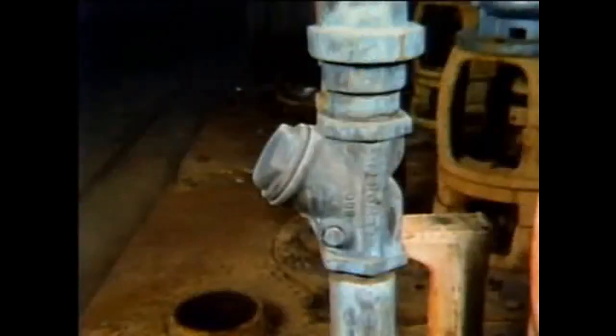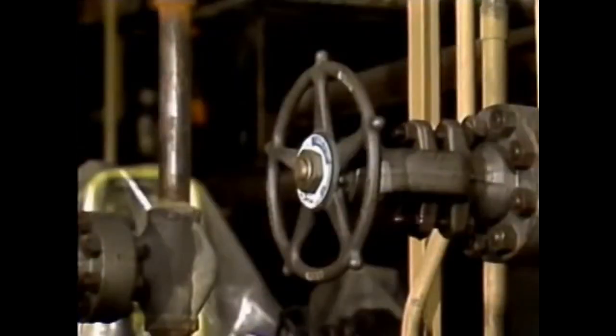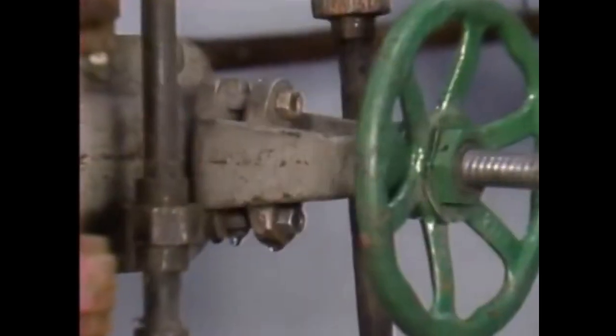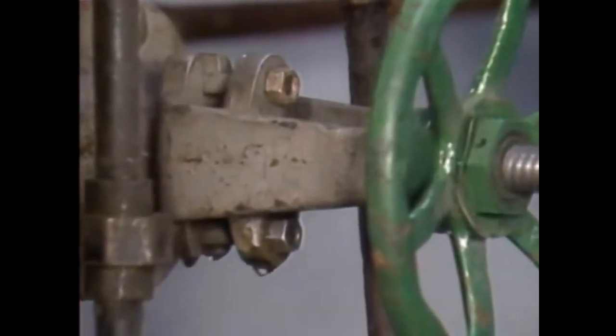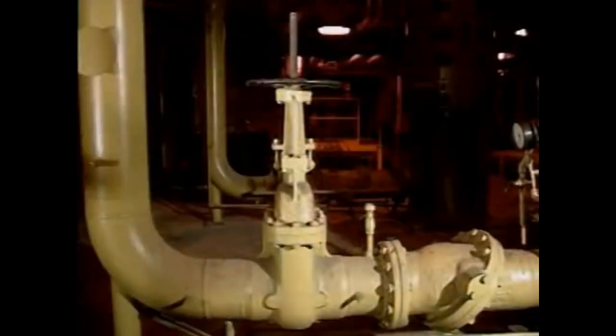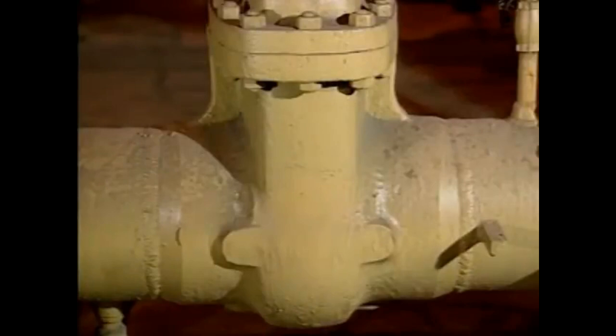Even though valves may look different, many types of valves have the same basic parts. Being able to operate valves properly and identify problems that may occur requires an understanding of valve construction. The main part of most valves is the valve body. This is the part of the valve through which the fluid passes. The valve body also contains some of the other valve parts and provides the means to connect the valve to other components. The method used to connect a valve in a piping system depends on system characteristics such as the amount of pressure that the connection must contain.